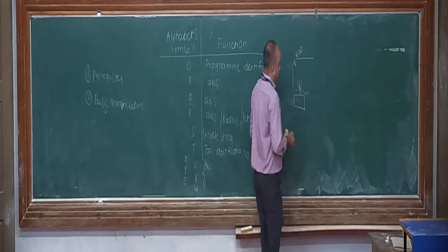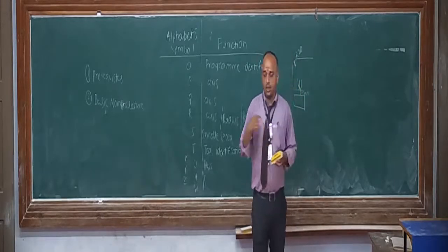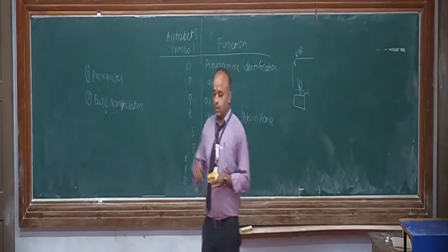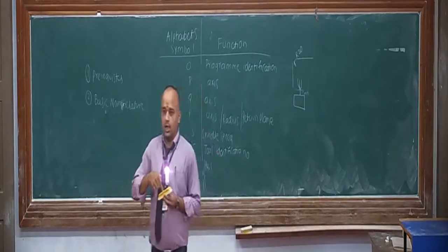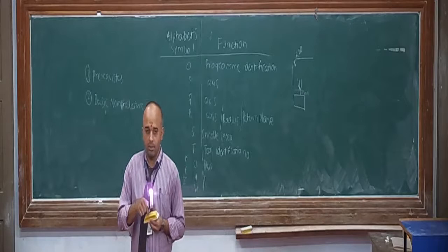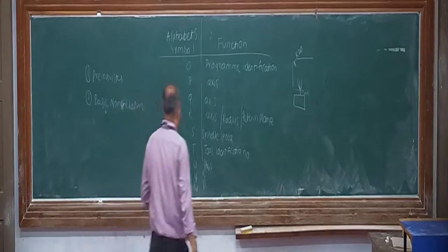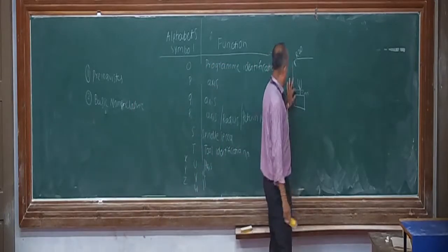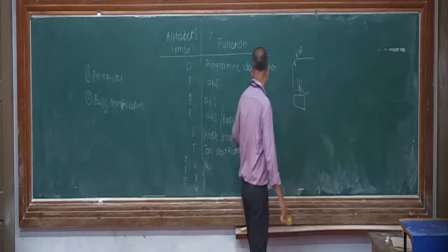So from there, the drill starts rotating. Feed and RPM are given, so it starts doing the operation as if it is operating on the workpiece. The point where the tool is slightly above the workpiece is called the return plane, and this is represented by R.